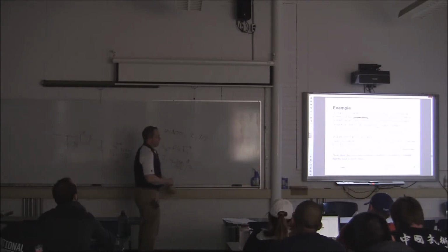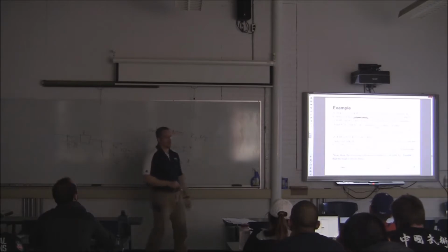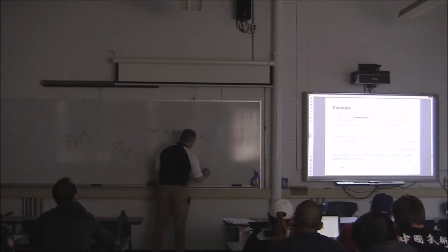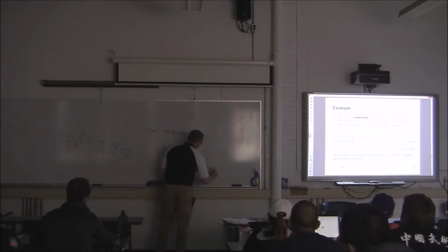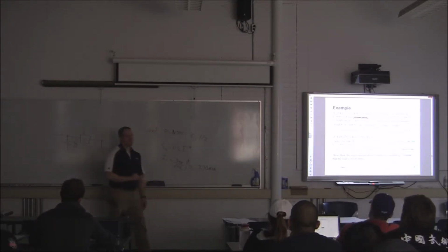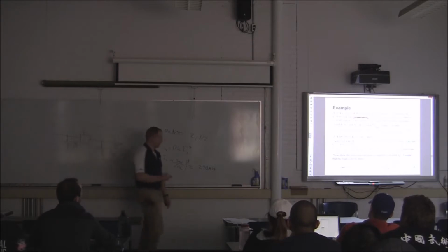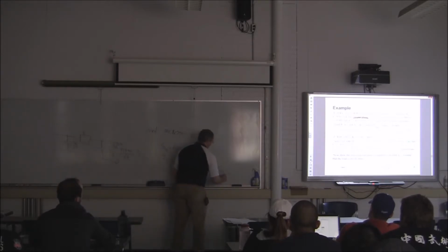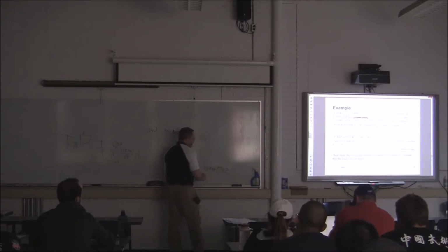S three-phase is 270 MVA. What is the inverse cosine of 0.8? 36.7? And it is a negative number.